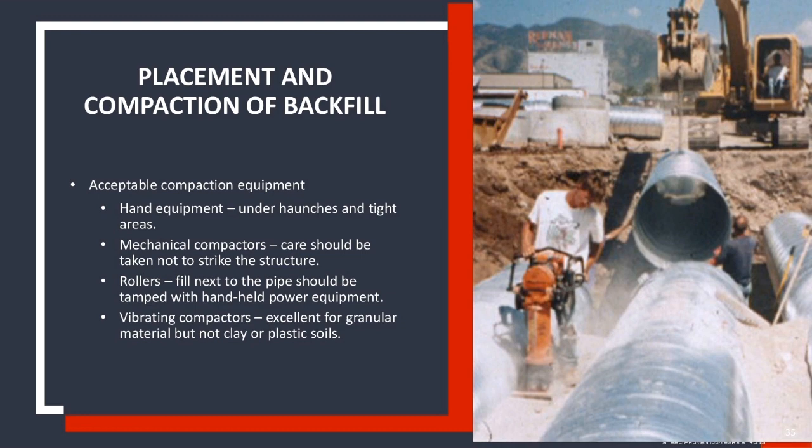So let's get into talking a little bit about equipment. I'll talk a little bit more about this later. But equipment plays a big role in the actual installation of the pipe. When you're doing the haunches, you're going to want to use hand equipment because that's really one of the most important areas of the installation. It's tight under there. It's hard to get to. So your mechanical compactors are not going to work. Your rollers are not going to work.